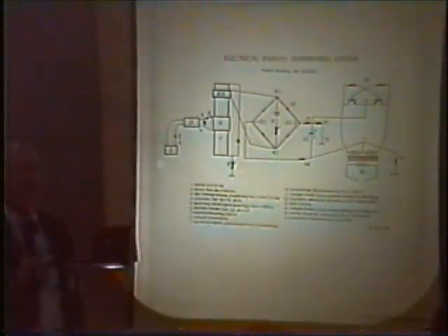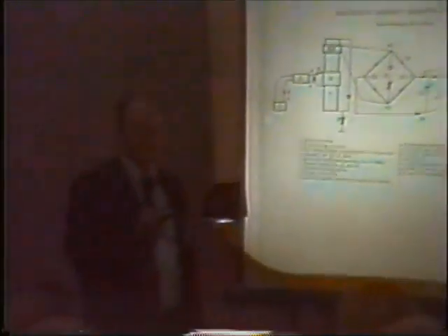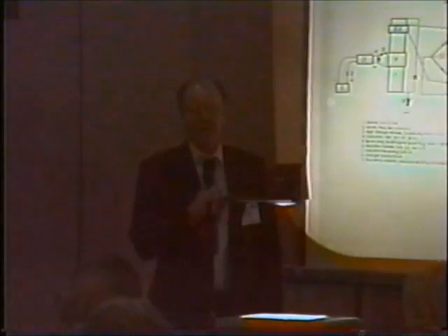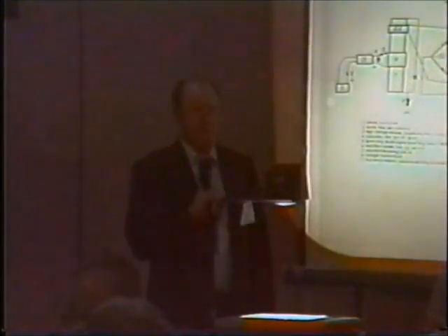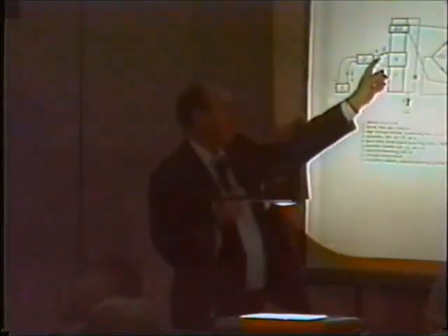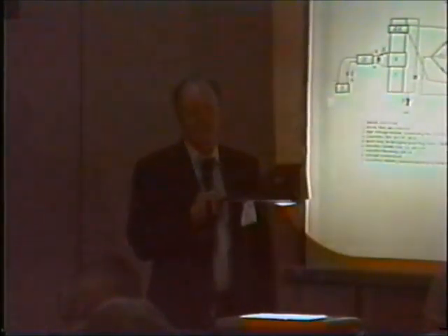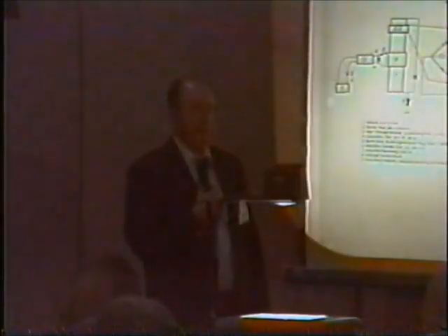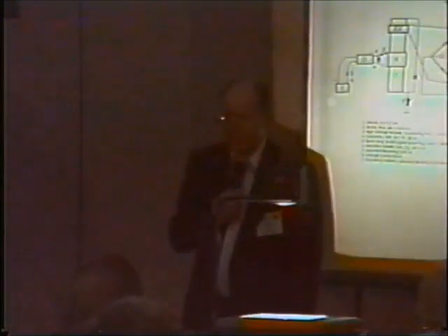I burned a lot of them up figuring out how to get things done, and this diode here was one thing that pretty well saves me. It prevents kickback, which destroys your high voltage laser module. It's on your plus side outlet of the battery. It does something else very interesting also.